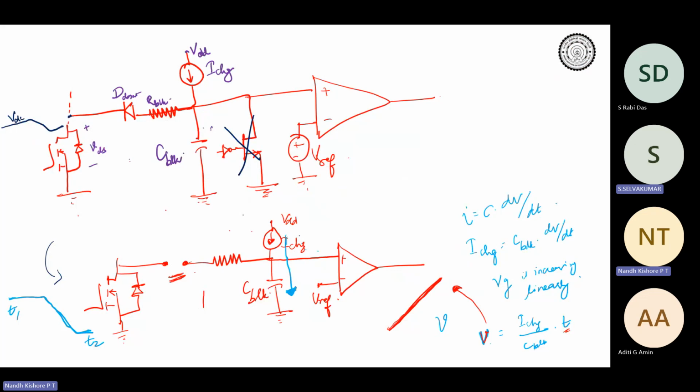So I have to make sure that I have the capacitor over here, and that the voltage increase during this period doesn't go so high that this voltage goes beyond Vref. You have to make sure that VC should always be less than VREF, so that you can prevent spurious triggering of the comparator. You don't want the comparator to false trigger. It should not sense extra voltage at the V plus terminal and give a fault signal. You understand, right?